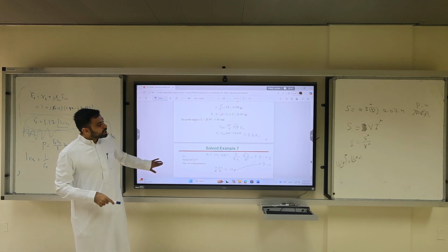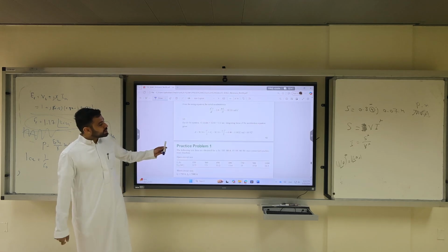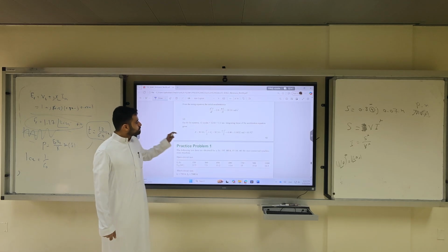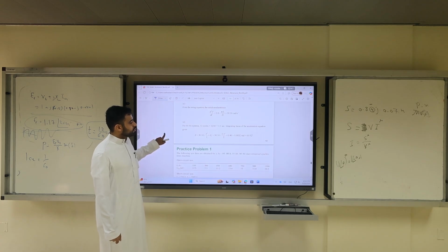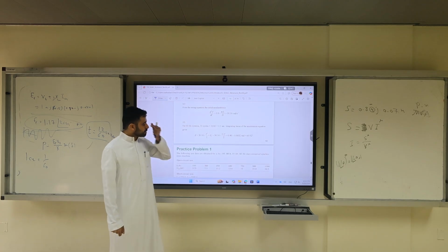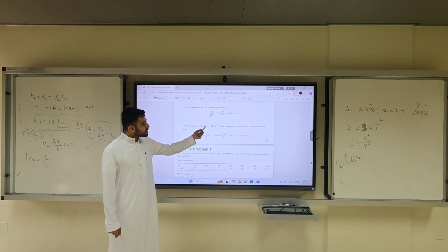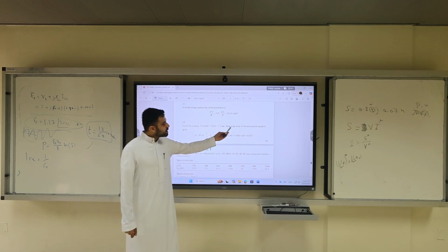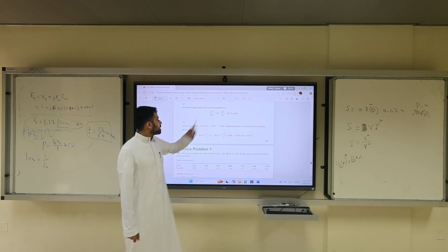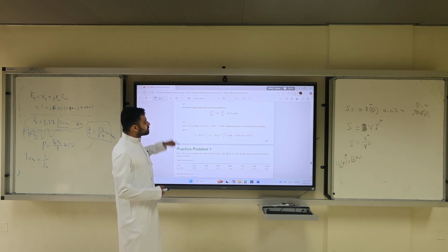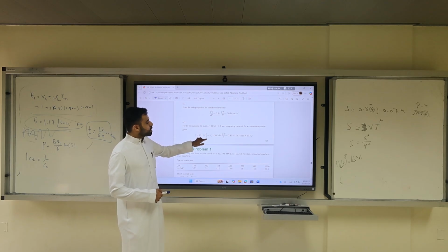So what will happen here in this part is I go back to the equation. Now he's doing things I don't like, which is integration. So for 60 hertz system, 12 cycles is 0.2 seconds. Integrating it twice to get the delta function, delta would equal the acceleration times t squared over 2 plus delta 0.